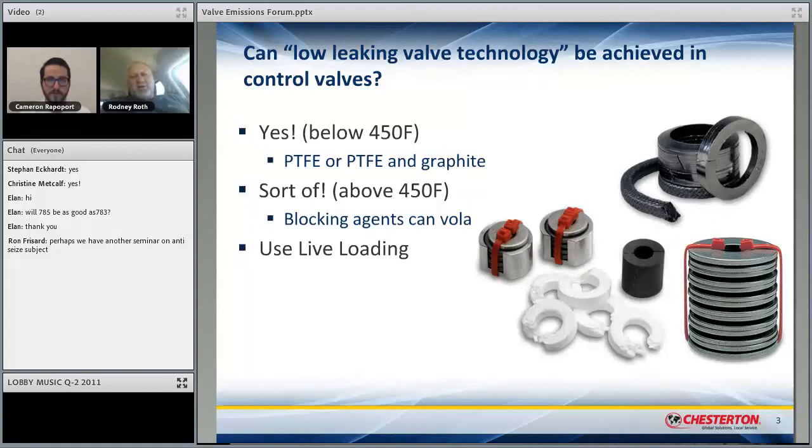So to answer the temperature question, there's 2 things. Number one, the 500 degrees was originally to be able to allow the use of methane safely. That's 600 psi, 500 degrees. You could test with methane safely. The API wanted to be able to use a hydrocarbon so that Method 21 monitoring could be used to detect the leakage, so that it would be closer in line with what is being done in the field when someone is monitoring leaks in the plant.